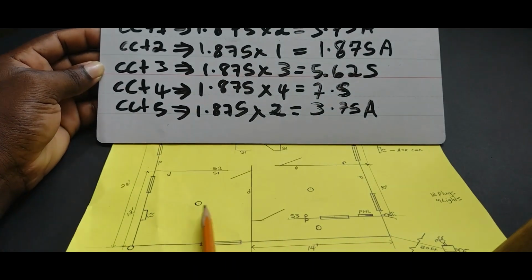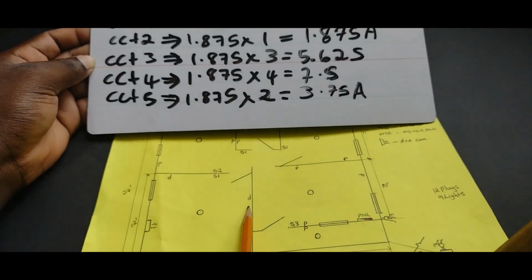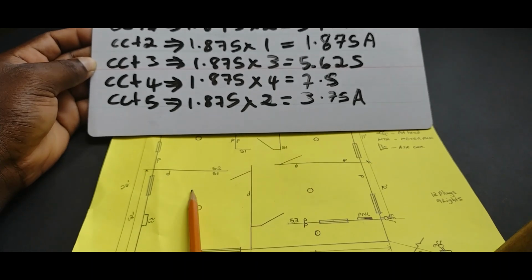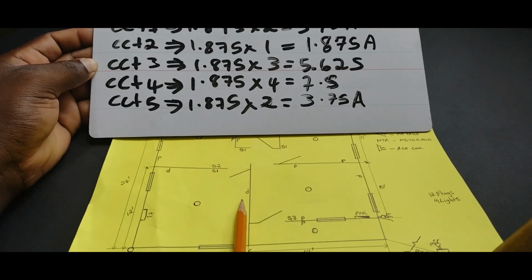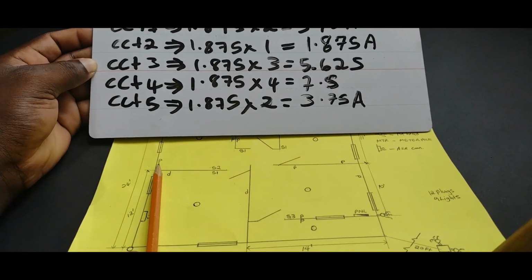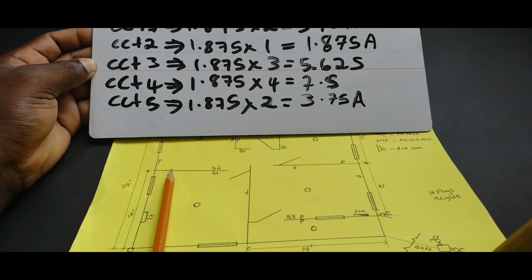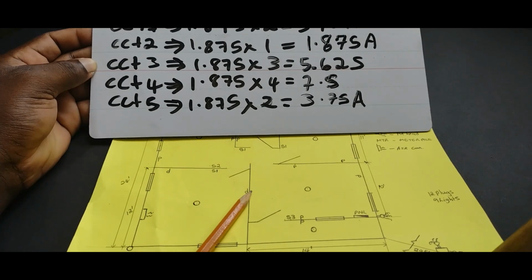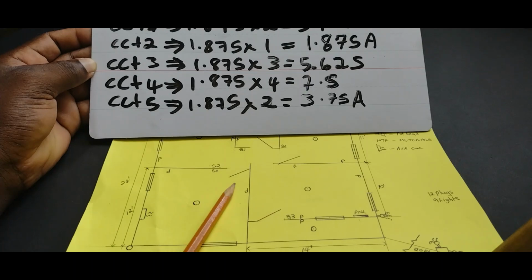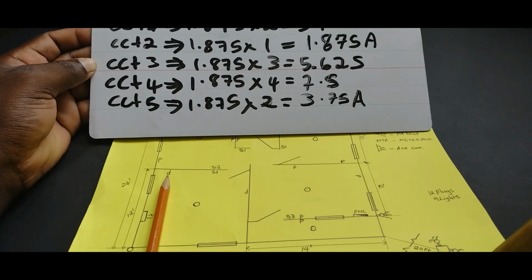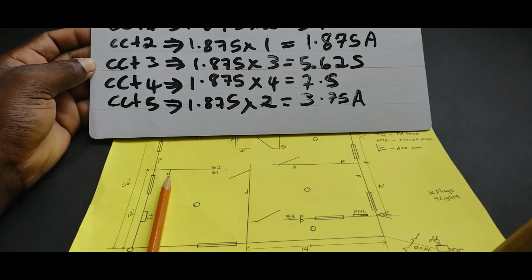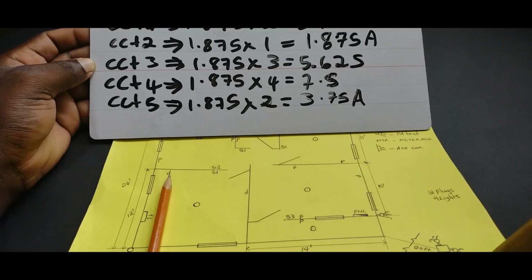Now the main bedroom, the larger bedroom, will have 3 plugs on its circuit. One from the kitchen, this one will be controlling the refrigerator, and another 2. Actually, the maximum for regular plugs on a circuit breaker is 5. But we normally don't max them out.